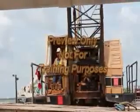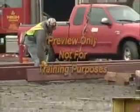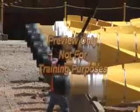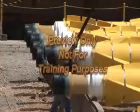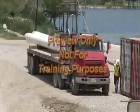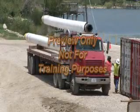Use hoisting routes which minimize exposure of employees to hoisted loads. Make sure your feet, hands, and fingers are clear of any pinch points before telling the signal person to OK the lift. When lifting in tight areas, stay out of danger zones to avoid crush hazards. No person should ever be directly under a load. Only personnel authorized and essential to the operation are permitted in the fall zone, but never directly under the load.